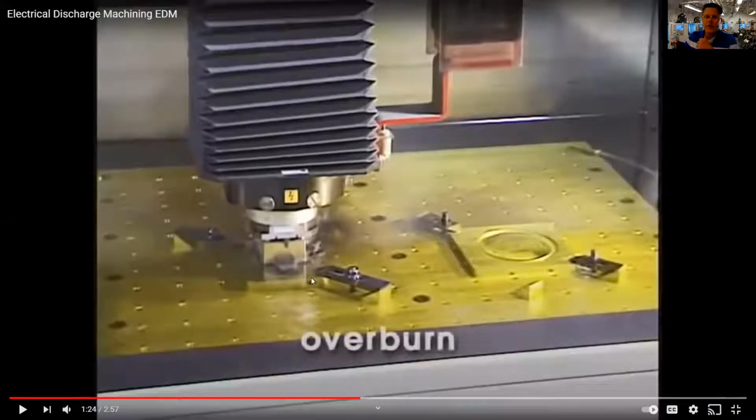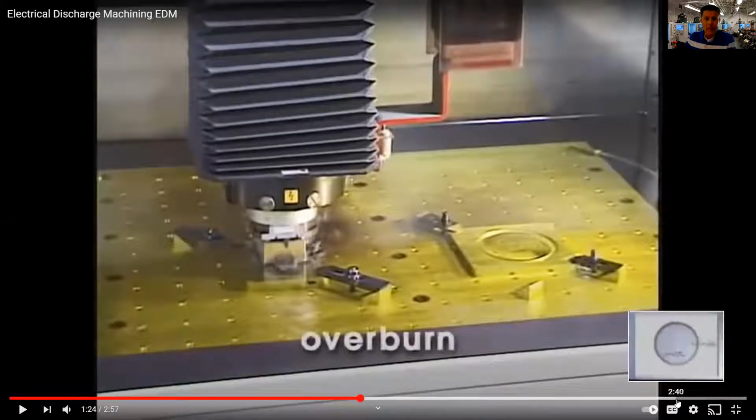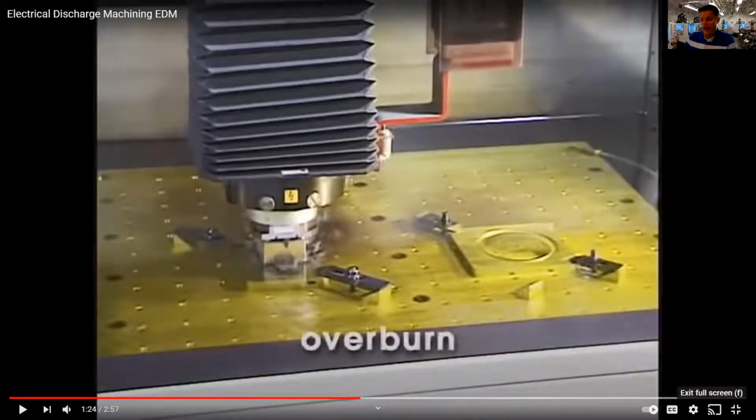So the rest of this video talks about what overburn is. What they're getting at is you have to make your electrode a certain percentage smaller than your actual feature, because when the spark jumps the gap, it's overburning or making the actual feature larger than the electrode. So there's an overburn percentage based off the current and frequency you're running, and you know how much to undersize your electrode, because the part then will become oversized right there. If you want to watch the rest of that talking about overburn, you have the link right there.